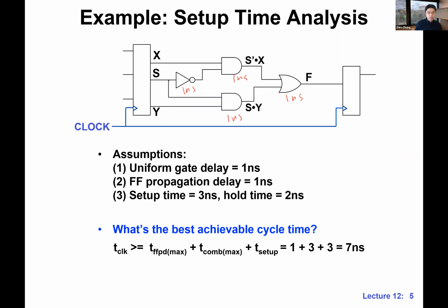If it's still not too clear to you whether we need a larger setup or smaller setup, hopefully this is clear from the inequality here. If we have a smaller setup time, effectively the best achievable clock period will also be shorter.